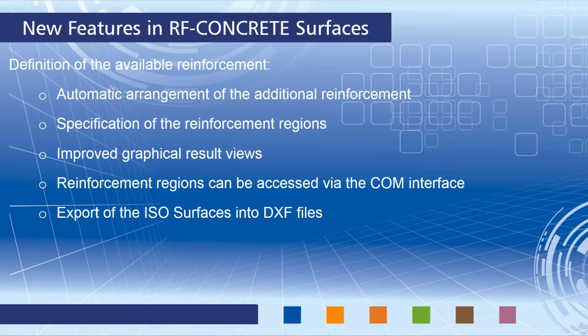We also improved the graphical result evaluation. You can see the reinforcement which is additionally required to your user-defined minimum reinforcement. You can also see the utilization of the defined lateral reinforcement. This is something you will also see in the example.